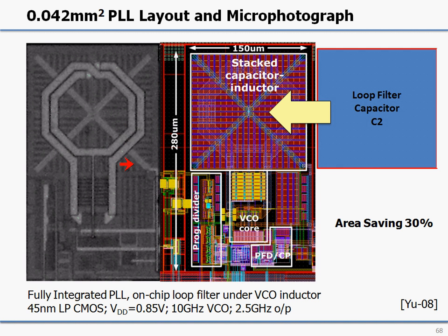In fact, what you notice is that the PLL area is really dominated by the oscillator. Here is the tank, and then here is the inductor, and then here are the variable capacitors that need to be contacted with a thick wire as well. The remainder of the PLL really takes a very small area and could probably even be laid out denser than in this example, and so we end up with a PLL that is very, very small, 150 micron by 283 micron.